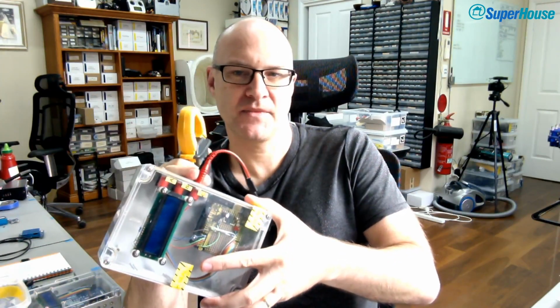So if you've got a 240 volt lead going through here, and you are passing 1 amp through it, so it's 240 watts, in this mode you would get 10 millivolts coming across here. So what you need to do is pass that into an analog input, read the 10 millivolts, and if you've got some kind of calibration on your input, you know what your reference voltage is, you can then read out the current that is being picked up by this.